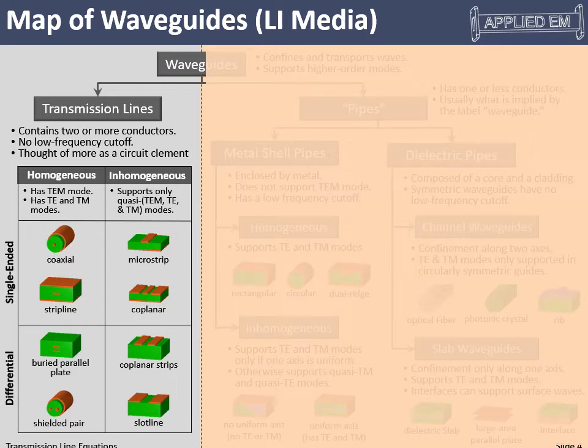And so we'll derive the resistance and inductance and conductance and distributed capacitance and these types of parameters. And once we have those, we can treat all transmission lines the same. It's just deriving those from the transmission line that involves an electromagnetic analysis, and that's what differs between the transmission lines. Deriving those from the geometry of the transmission line, that's reserved for a later lecture.